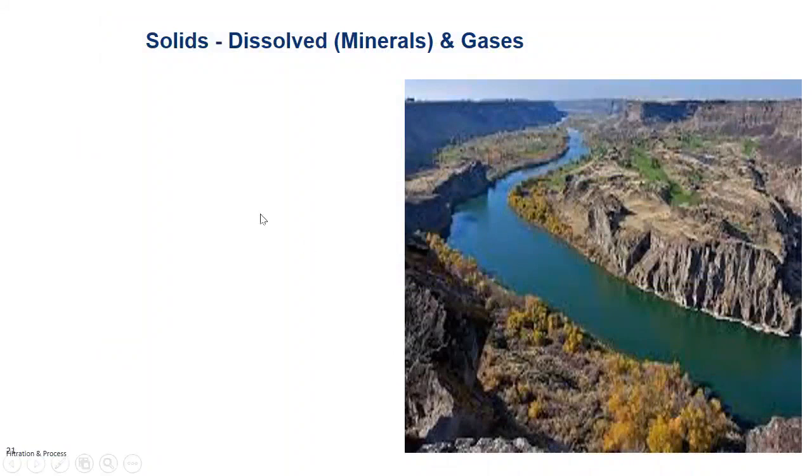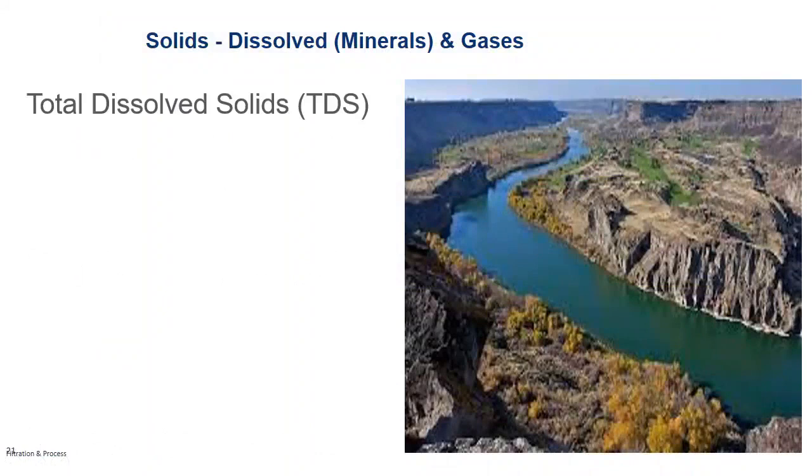Now, what does dissolved minerals mean? This means total dissolved solids. This is anything in the water with a charge. Okay, there are some organic molecules that will carry a charge. They will play a role in this number as well. They tend to be slight in amount. But this is mainly your dissolved rock, which breaks apart in water into its dissolved salts.